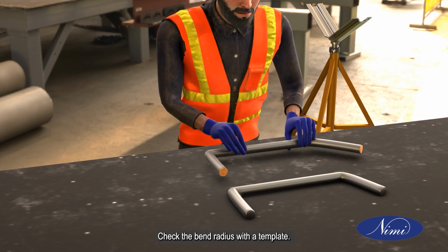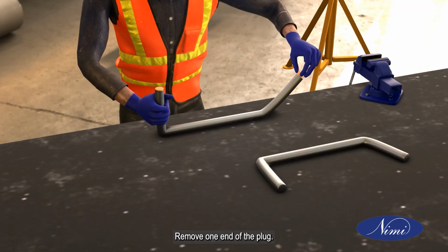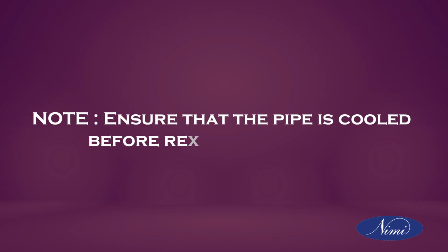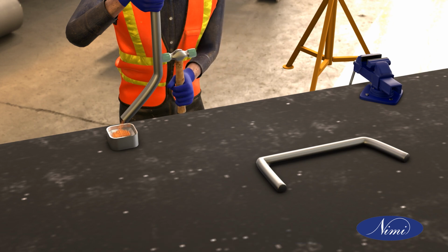Check the bend radius with a template. Apply heat throughout the whole operation and overbend slightly and straighten out the final bend. Remove one end of the plug. Note: ensure that the pipe is cooled before removing the plug. Remove the sand by tapping the pipe gently with a hammer.